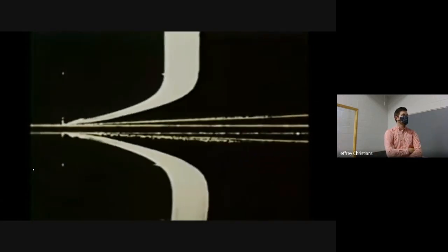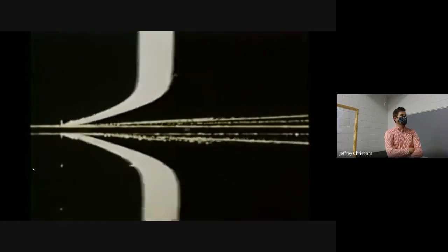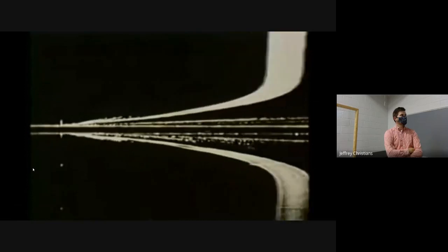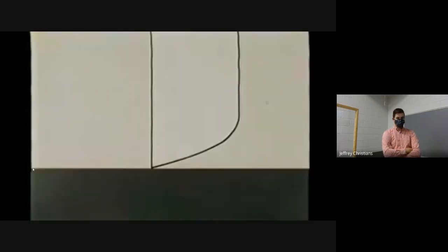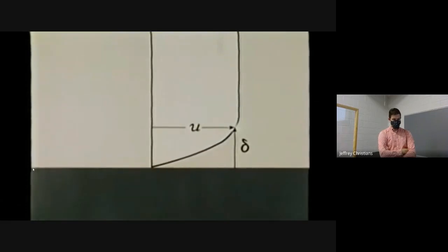The velocity throughout the boundary layer is less than that in the previous screen. There is no slip between the plate and the layer of fluid immediately adjacent to it. At the plate, the relative velocity is zero. This is the no-slip boundary condition of viscous flow. The displacement of the bubbles corresponds closely to the velocity profile in the boundary layer.